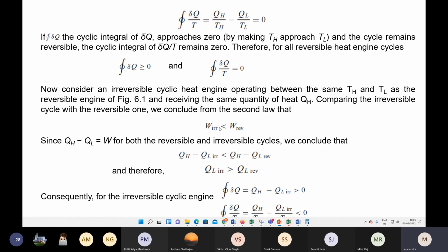Okay. Then instead of these terms, we are directly substituting heat terms. Okay, but anyhow, the source is the same that we are considering. Okay, the source is the same. Why are we considering the source the same? In case of both the engines, you are burning the same fuel at the same stoichiometry, and the same mass flow rate of the fuel. Mass flow rate of the fuel means the same thermal input you are providing to the engine. That's what we are considering, QH as the same. That could be any engine, gas turbine engine or thermal power plant or IC engine.